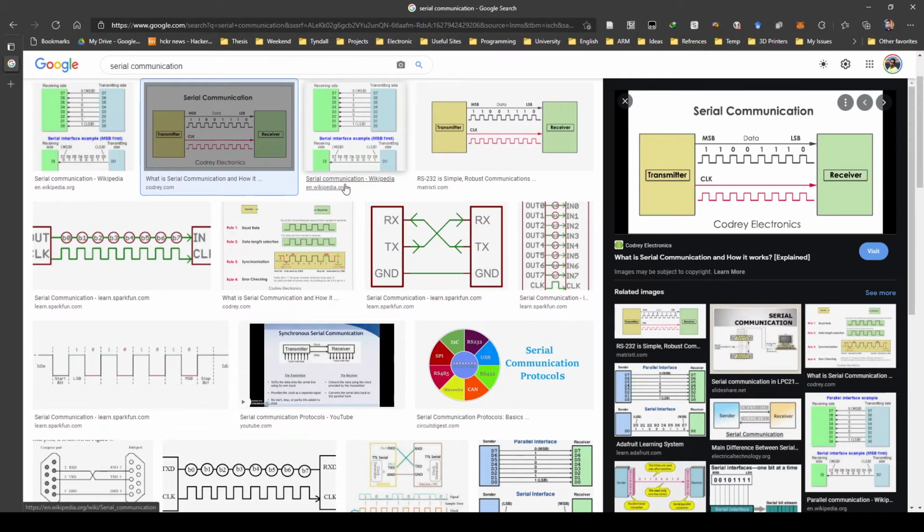Basically, using the same principle, let's say in simple terms, you can turn on or turn off a pin. By turn on, we mean that you will connect that pin to 3.3 volt in our case, or when you turn it off, you just connect that pin to the ground, which is 0.